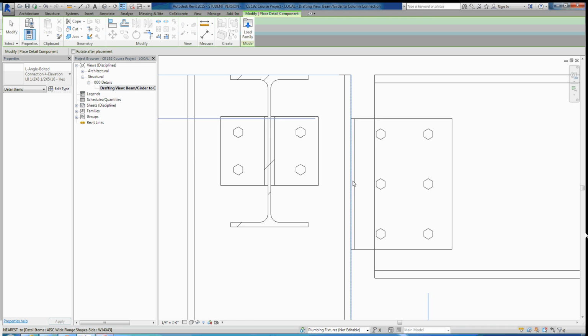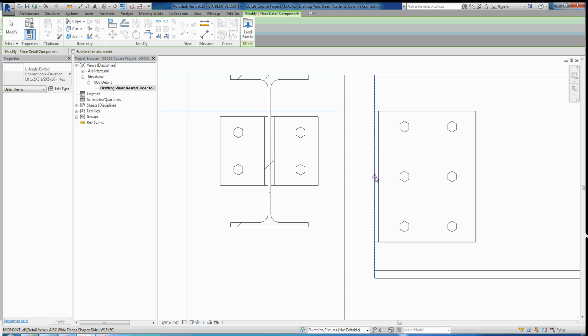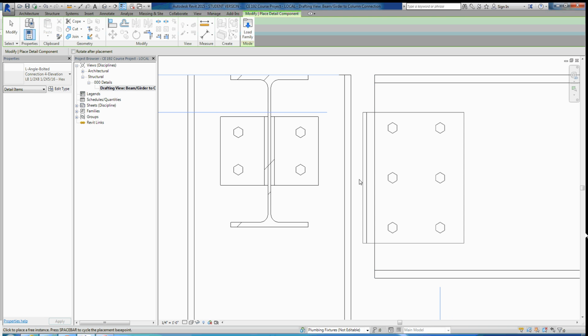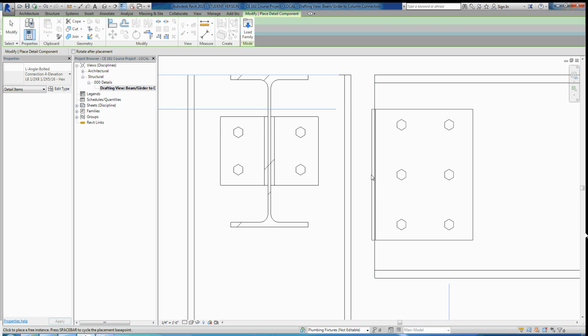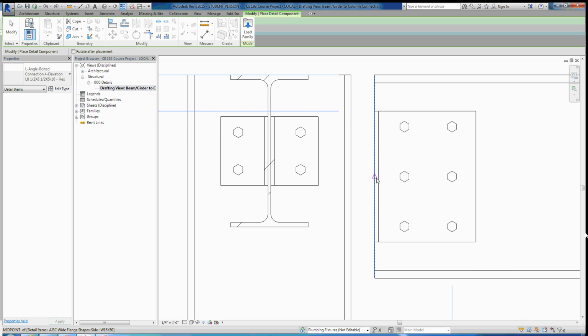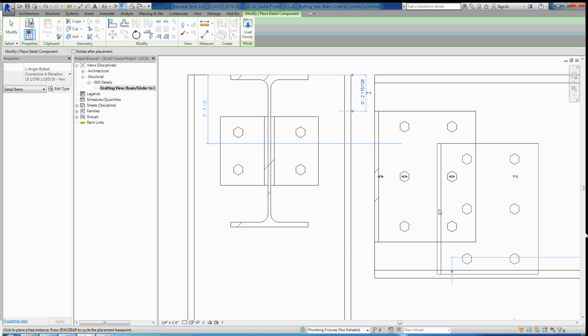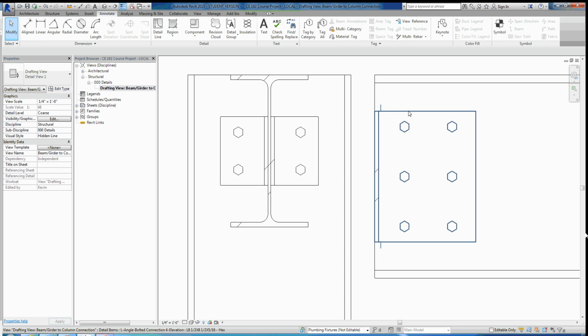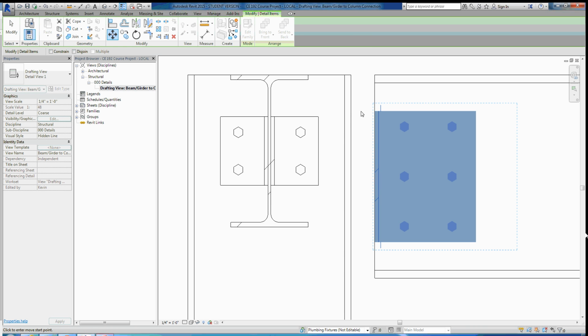You can see that it's not going to line up nicely for us on the midpoint of this girder. We can't have an extension come over here. So again, I'm just going to click it right at the midpoint here and do an intermediate step to move it to the left. I'm going to lock it to the midpoint of that girder there, and then I'll click our angle, hit Move, and just move it to the left here.